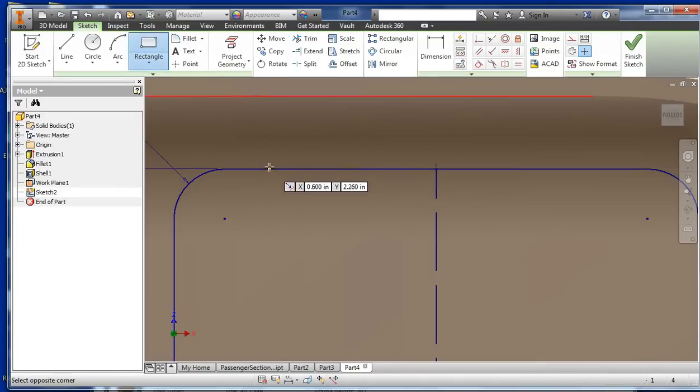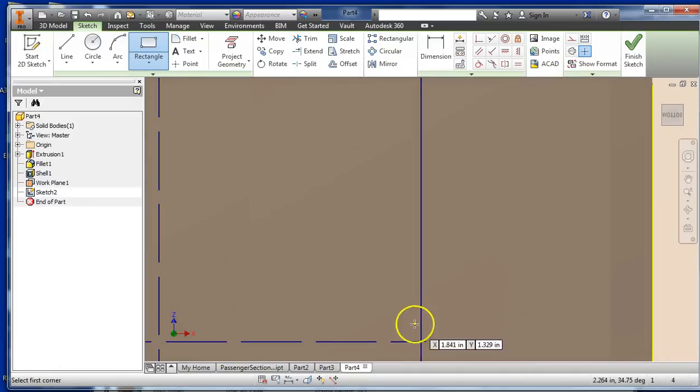And I'm going to have a rectangle constrained to this top, and I could see that the distance parallel to this outer wall was supposed to be 0.05, and it was supposed to protrude away from that edge 0.04. Okay, we'll come over here and make one more rectangle, the same dimensions. 0.05 parallel to and 0.04 away from. Okay, and I'm going to purposely kind of stay away from there so I don't create any constraints yet, and we'll move it into place in a second. So away from that side 0.04 and 0.05 along.